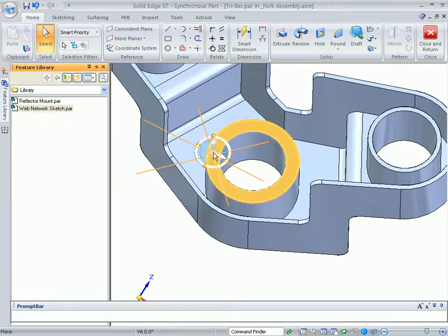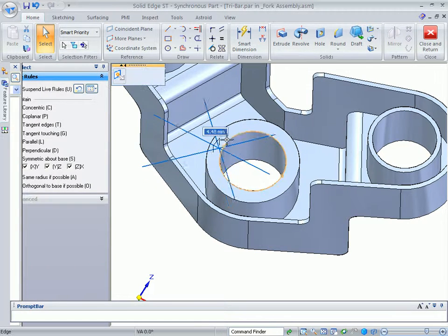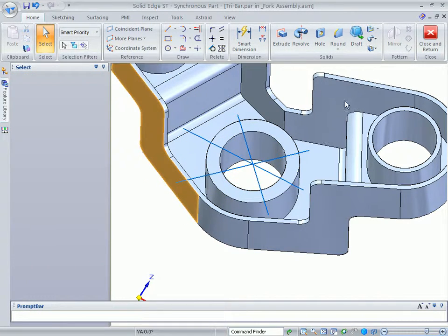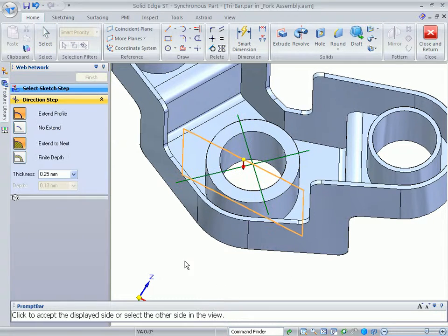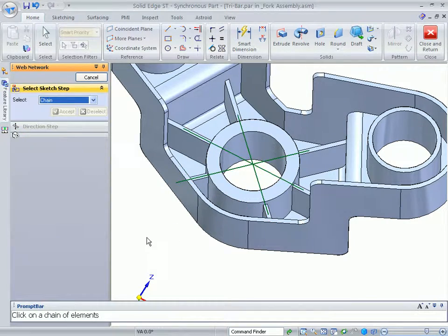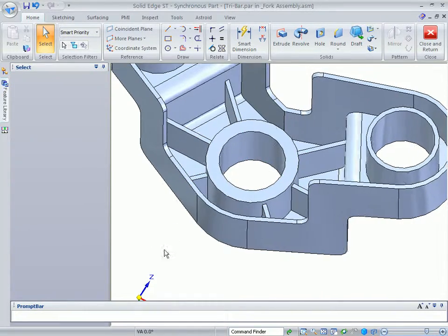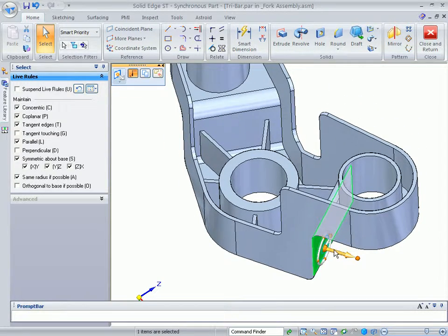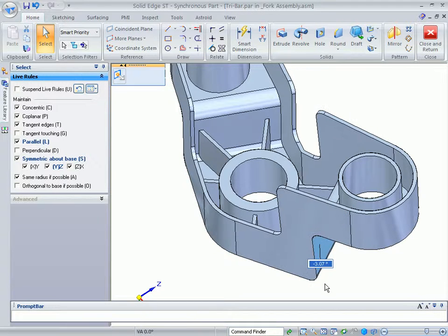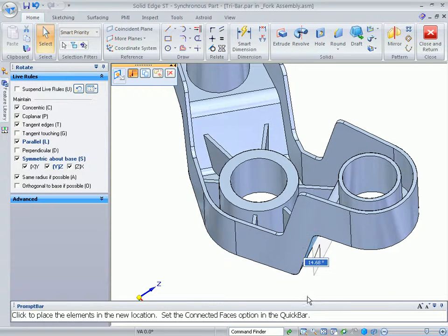We'll add some stiffening ribs, starting with a sketch retrieved from a library. Because thin wall operations in Solid Edge are procedural, users have full edit control without model regeneration. As we taper the vertical face, notice how wall thicknesses and symmetry are preserved. These edits happen without regenerating the entire model, but in a history-based system, this simple change would force a costly rebuild on the entire shell and rib operations.